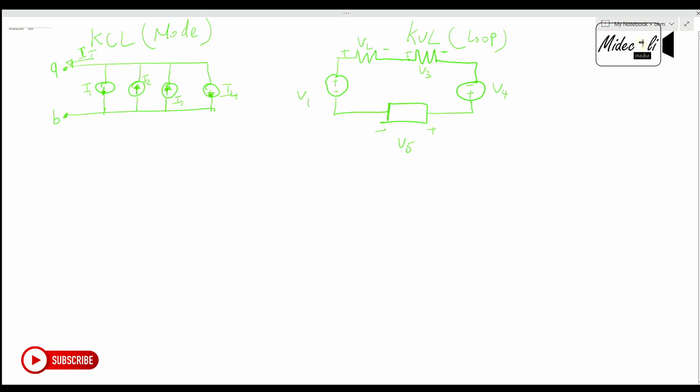Today, under Fundamentals of Electric Circuits, we are going to be looking at KCL and KVL, which is Kirchhoff's Current Law and Kirchhoff's Voltage Law. Kirchhoff's Current Law states that the sum of current entering a node is equal to the sum of current leaving a node. You see that word node, underline it. That's a very key word in stating the law of KCL.